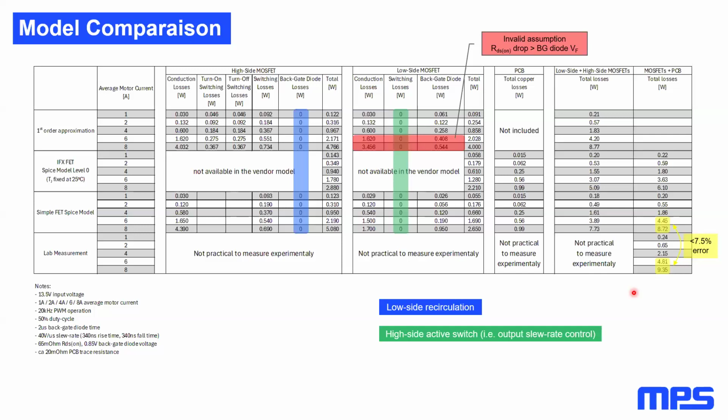This phenomenon, if exasperated, could bring to the point that the RDS voltage drop could approach the body diode forward threshold. That means that the body diode could start conducting even outside of that time, in parallel to the RDS(on) of the recirculating MOSFET. This situation is equivalent to reducing the RDS(on) by allowing an alternative path to the current flow. And the net result is that the losses in the recirculating MOSFET actually decrease.